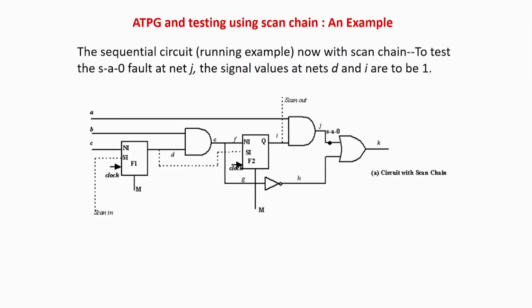For a sequential circuit, you should have scan to go into the circuit, and the philosophy of fault model is mandatory to do test in a reasonable amount of time. So whatever you do, these things have to be done. Now we are going to see with an example how scan has to be done. We are taking a very simple circuit and a stuck-at 0 fault over here. Same problem as you have seen, there are 2 flip flops in a chain in sequence.